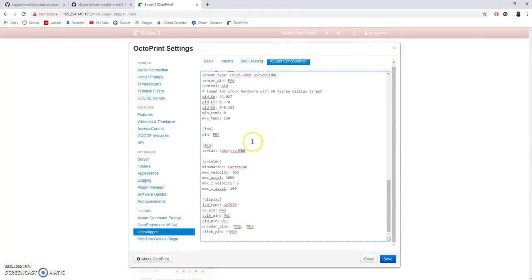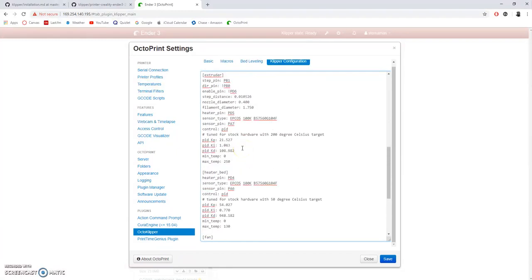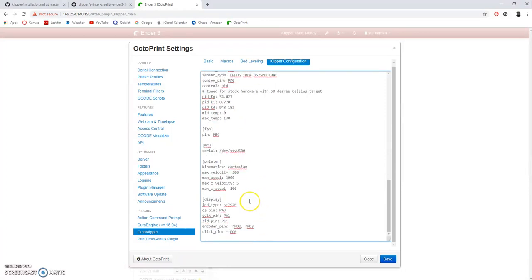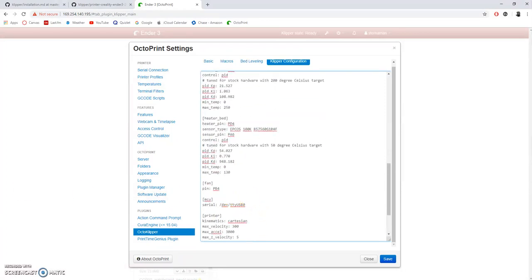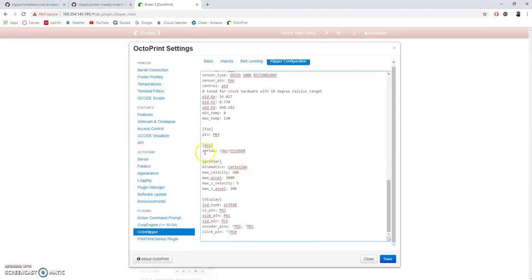But one thing I would like to point out with Klipper and the Ender 3 in general is a few questions I have been receiving regarding what's the best settings, share your config, we want to know what you've been struggling with. Well, one thing's for sure I just want to share is that the printers, especially like the Ender 3, ship with not the greatest quality control. A lot of dimensions and a lot of parameters are different intra-brand between these printers. So my pressure advance setting that works for me may not work for you. That's more or less why I haven't really shared my settings. It's just really simple, you know.